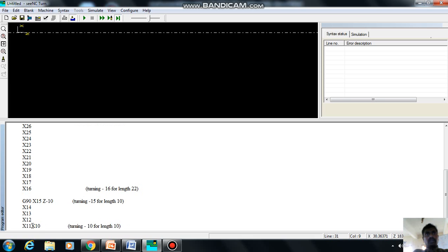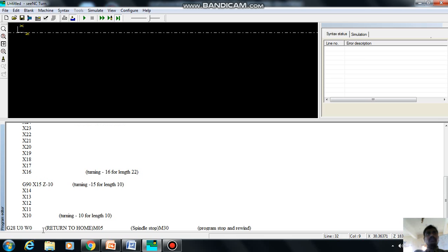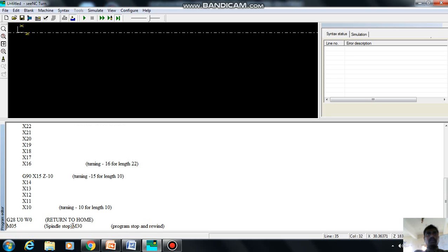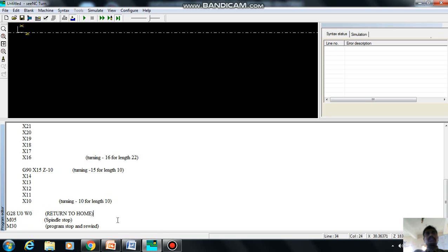Okay, that's done. Once the program is done, then G28 U0 W0, return to home, M05, and M30, right? So this is what is being done. Once this is over, then we have to go for syntax.